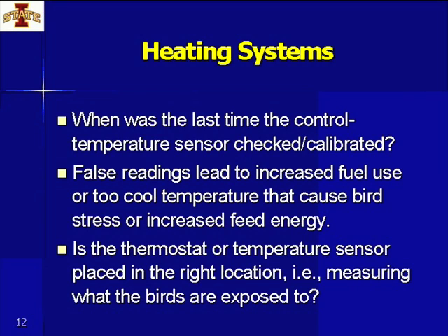Okay, so heating systems obviously are a very important part of this, and here are just a few things that producers should ask themselves. When was the last time the control temperature sensor was checked or calibrated? I think Larry touched on this already. And false readings obviously will lead to an adverse effect on bird performance and energy efficiency.